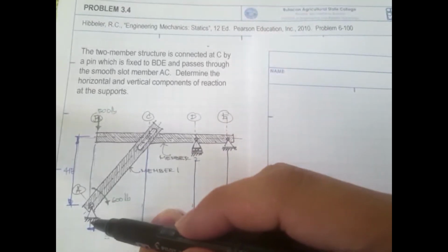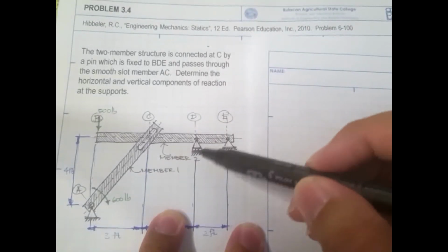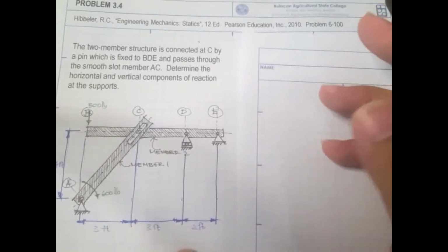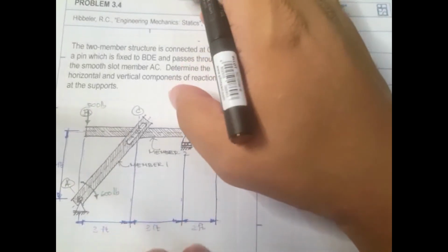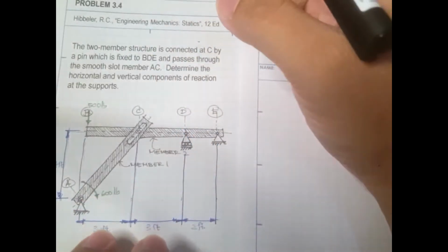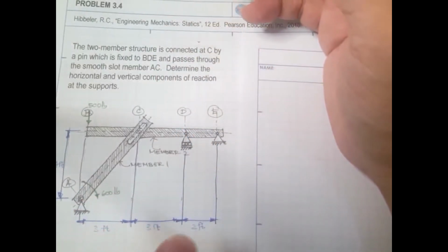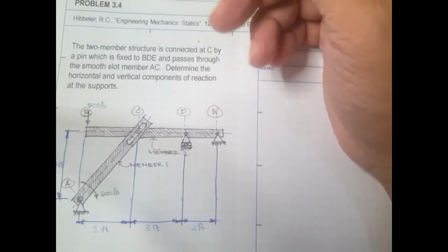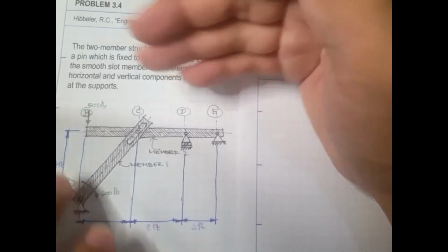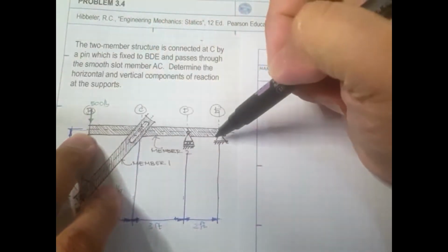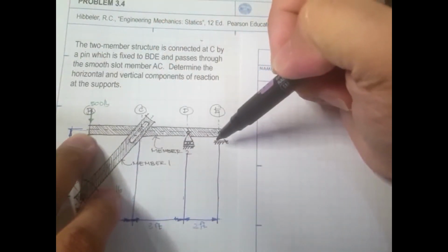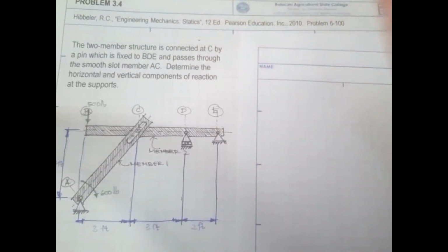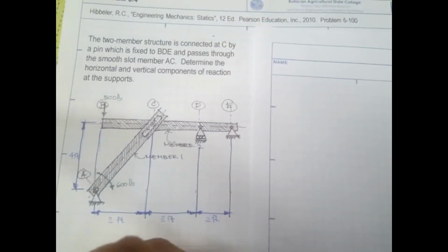So right here, this is a pin support, this one is a roller support, and this one is a pin support. Now, although the problem says that we are only to find the components of the reactions, I'd like to draw the internal force diagram for each of the members. So if this member is experiencing, let's say, axial or shear and moment, then we have to draw that. Okay, so for the solution,